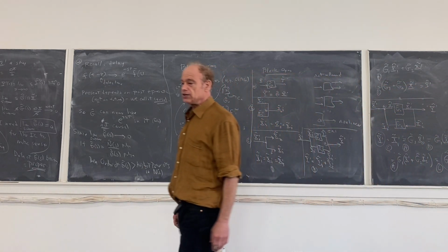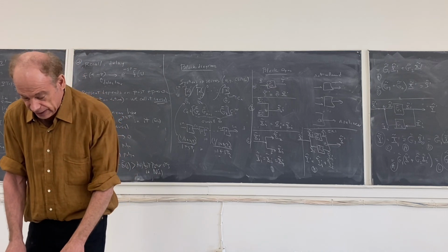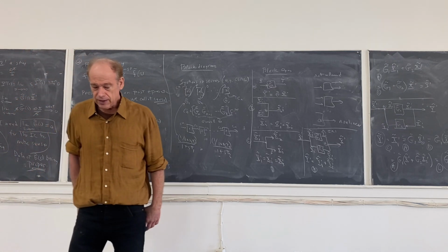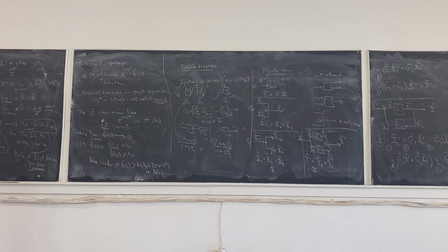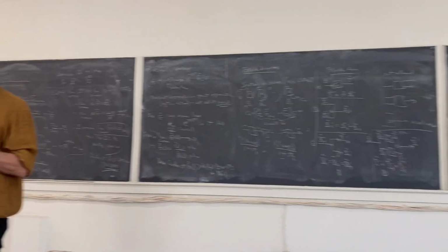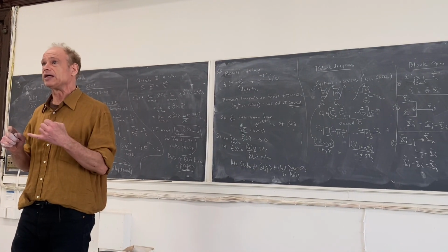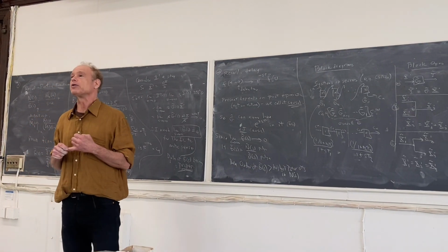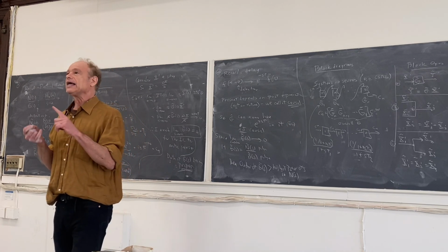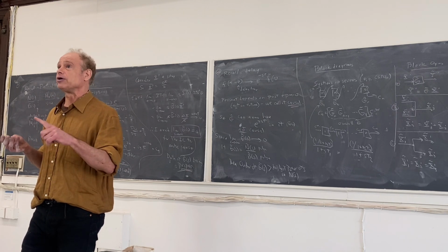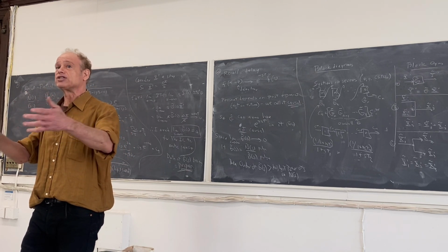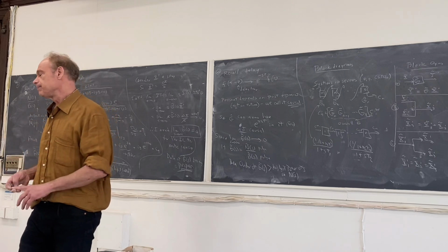So just before we finish, a couple of little coming attractions. What we said in the beginning of the hour is that a lot of times we can get all the information we need, as opposed to all possible information, all the relevant information from the Laplace transform without inverting. Is it stable or is it going to blow up? That's what we've looked at. Is it going to oscillate or not? Well, that depends on whether the roots of the denominator are complex or real.